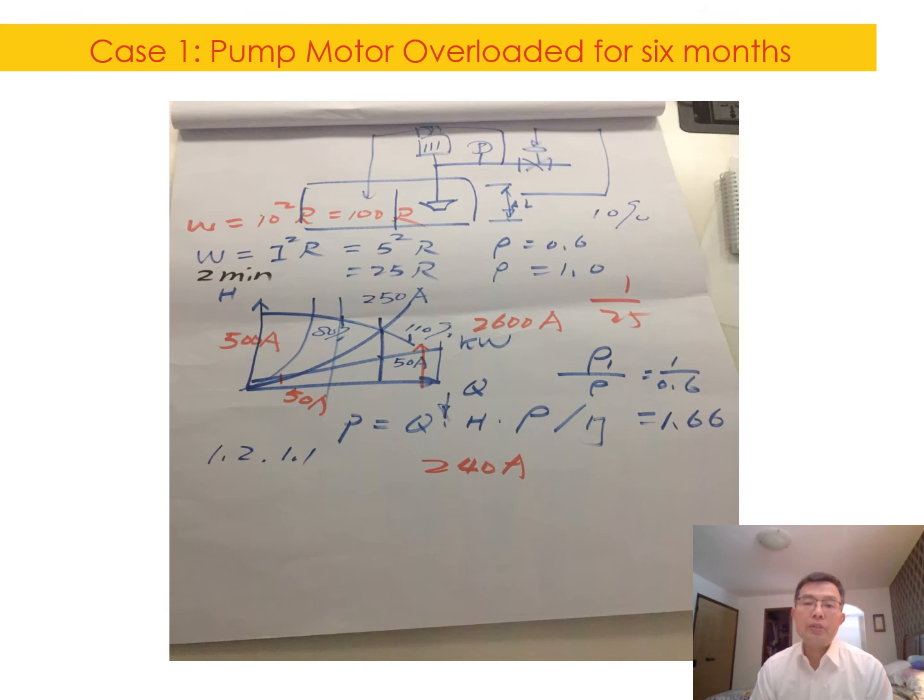And then what we did there is we asked the team over there to close the discharge valve 100%, and then after the start of the pump, gradually open the discharge valve. Because what we can change here is we can dramatically reduce the flow, and in that way, the power needed for the pump at startup is at the minimum, right? So after they prepared, half an hour later, they started the pump. It got through and gradually pumped the water out, then the condensate came in, then the motor ran smoothly over there, right?